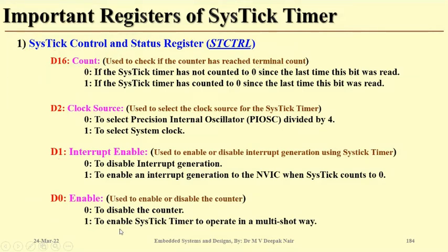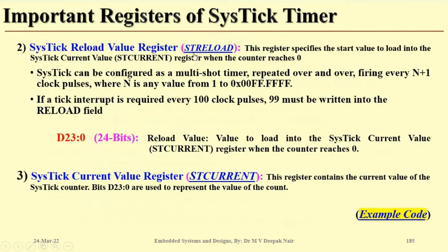Now, coming to the next register, Systick Reload. Remember, this is a 24-bit counter, so you can load a maximum of FFFFFF. This register is used to load the count. It specifies the start value to load into the Systick current register when the counter reaches 0.